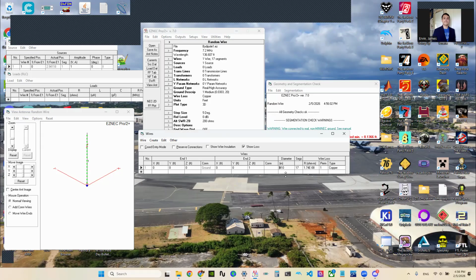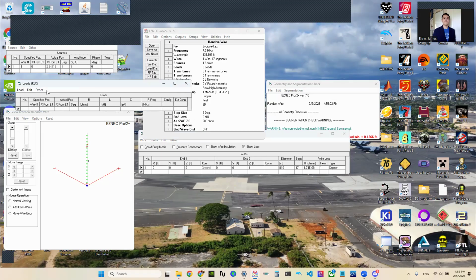So this would have been useful for winter weather, for stuff like Winter Field Day. Say we were to build an antenna or want to see how an antenna would behave. Say you have a dipole you're a big fan of. You can model it, see how it would behave, and then see how it compares in actuality. One of the things you can do, there's a number of antennas called trap dipoles, where you have a capacitor and inductor in parallel.